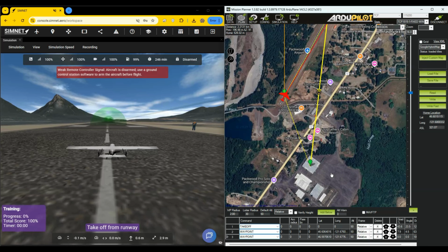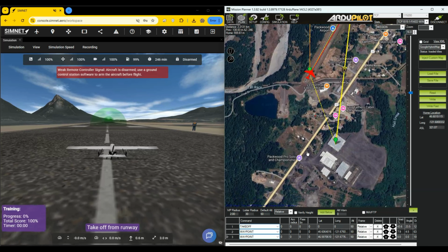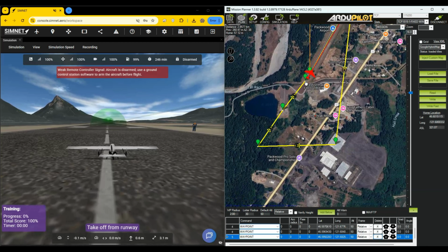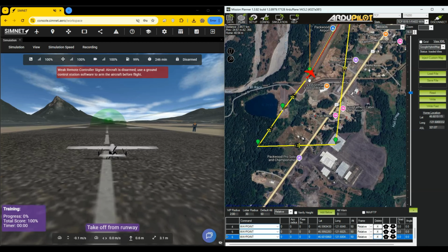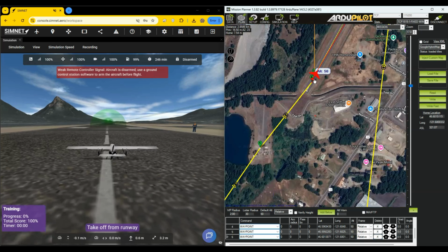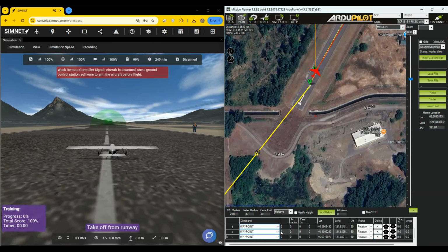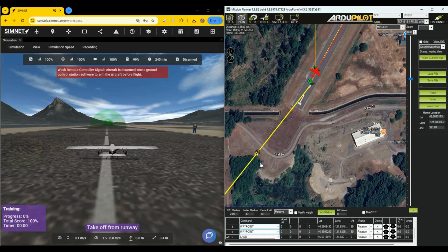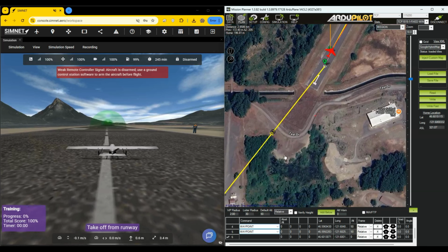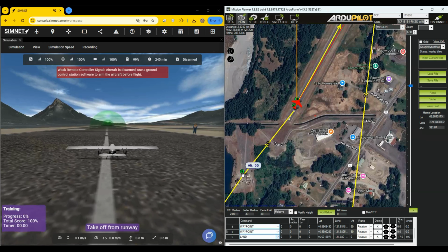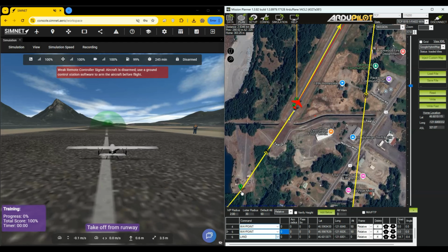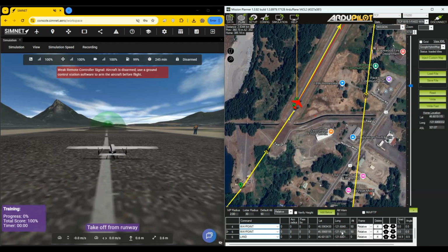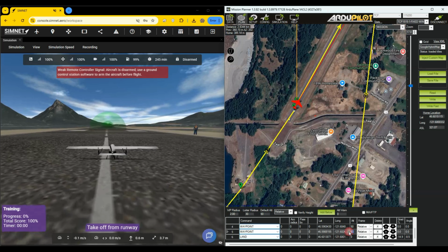To plan the runway landing, place 3 waypoints in a straight line aligned with the runway. Position the last waypoint to the desired touchdown spot at the beginning of the runway and convert it to a land command. The waypoint before it tells the aircraft when to lower its throttle and begin the final descent. Set the position and altitude of this waypoint to achieve a gentle 5-degree descent path. In this example, we're using 30-meter altitude.